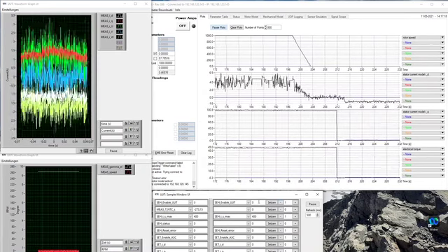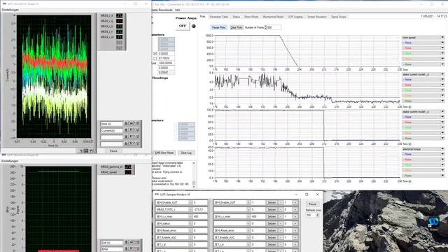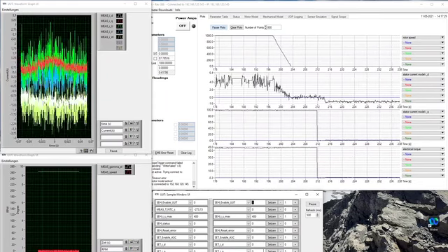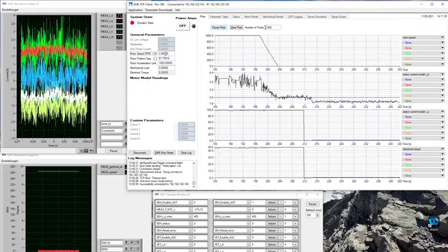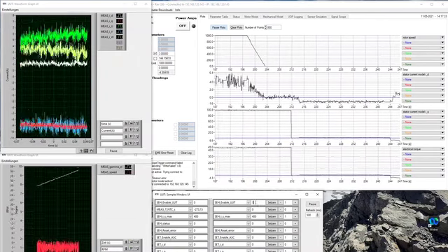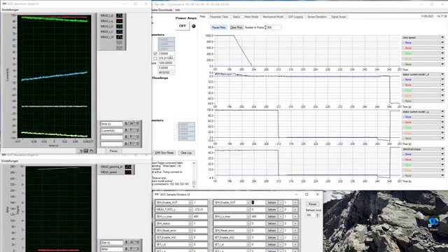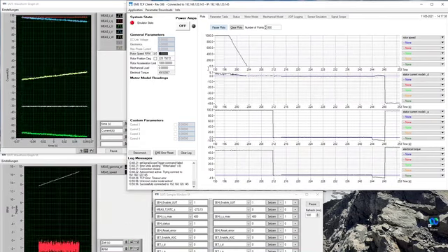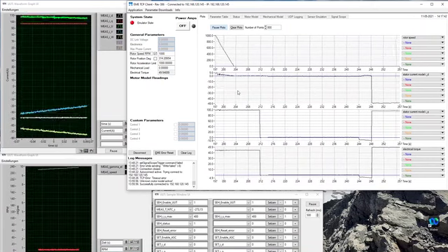For the second test of the low voltage HIL, we would like to show the torque control mode of the inverter. So the inverter is set to torque control mode accordingly. The initial rotor speed is set to 3 RPM and the initial torque set point is set to 50 Newton meter. After enabling the UUT, the actual electrical torque reaches its set point of 50 Newton meter. Then the rotor speed is increased to 1000 RPM.